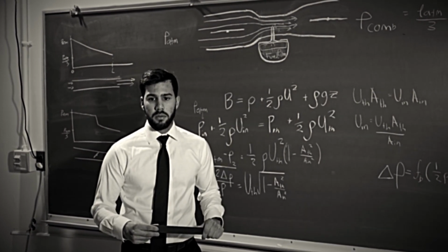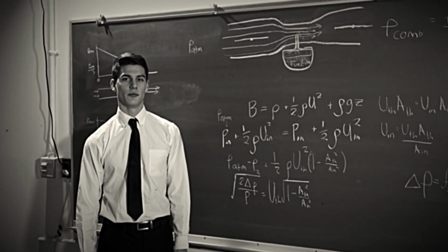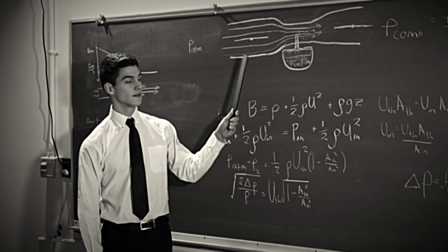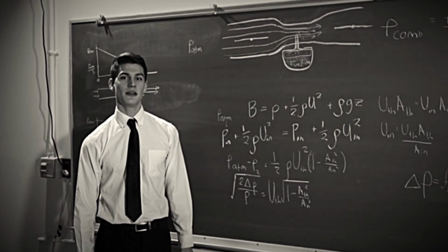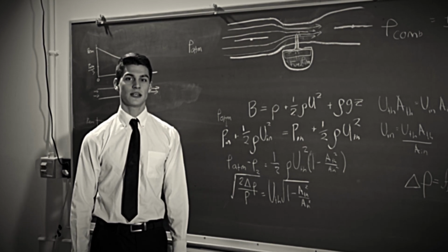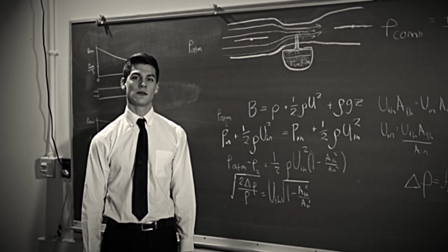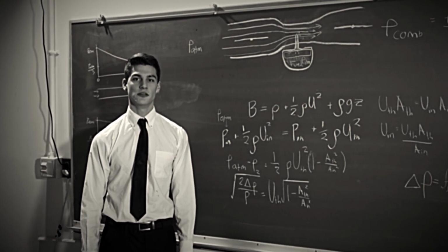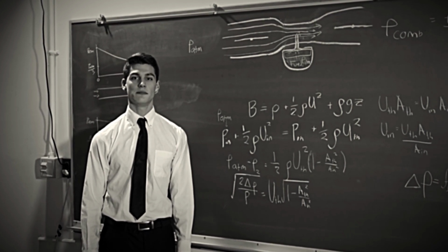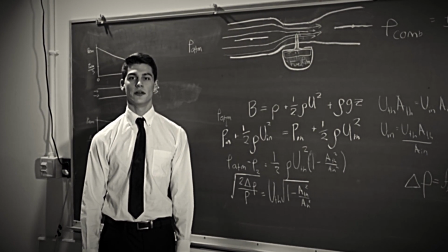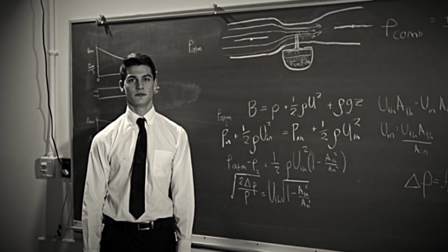and into the flow. The geometry of the carburetor is specifically designed for 2 purposes. First, the converging region at the inlet minimizes viscous losses as the speed of the flow increases. Secondly, the cross-sectional areas and resulting pressures are tuned to stoichiometrically optimize the ratio of fuel to air for combustion. Ideally, the fuel-to-air mixture remains constant as mass flow rate through the carburetor varies during engine operation.